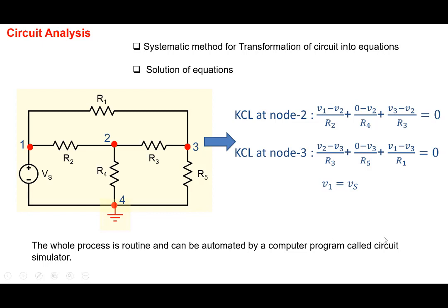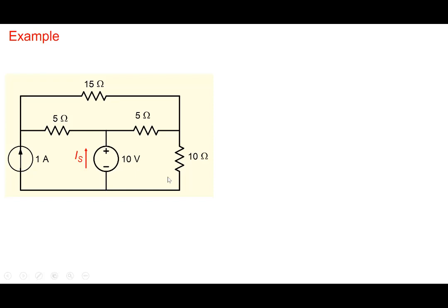At the end of this particular lecture, we'll see how a circuit simulator works, an example of a circuit simulator. All right, so transformation of a circuit into equations. That's the first step in analysis, and the nodal method allows us to do that in a very well-defined manner. So let's take a concrete example and work it out.